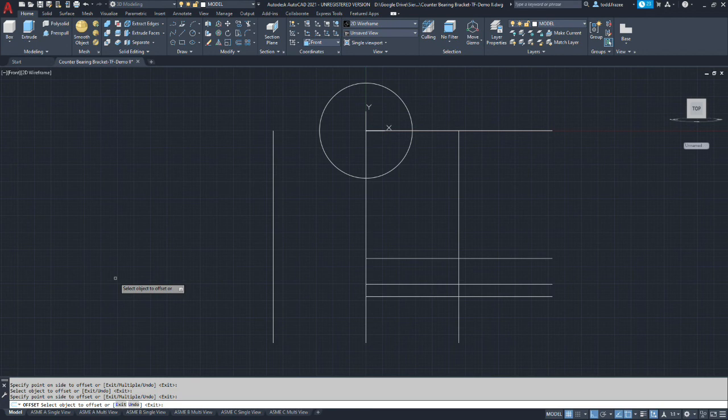Okay, the next series of lines we're going to develop are the lines that make up the little T flange on the base flange. It gets to go in a slot, and it has a tight tolerance. It's 38.1 millimeters to 37.95 millimeters. Now I believe it's best practice to model the part at the middle of that tolerance range.